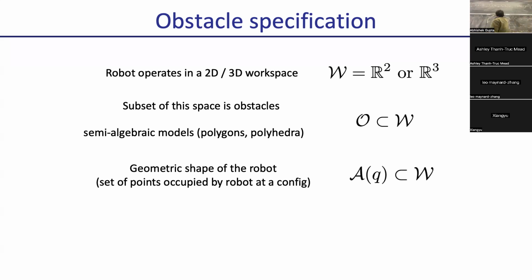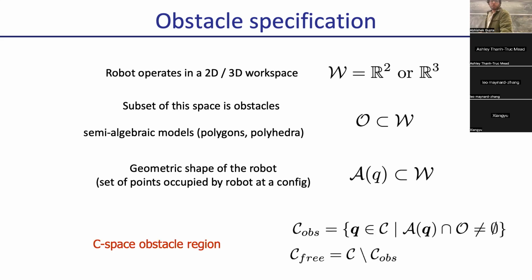And so this thing lives in configuration space, like in R2, right? And you're going to have some A(q), which is going to be all of the points in world space. What you really want to do is find a path through this configuration space. You want to find a series of configurations of your arm so that it does not collide with any obstacles. And that means that no point inside A(q) collides with any obstacles. Does that make sense?